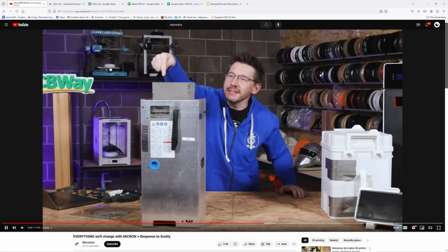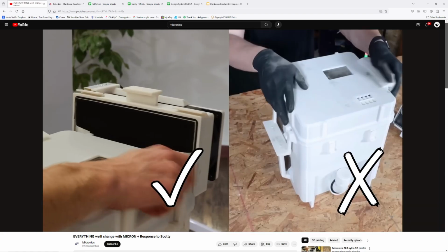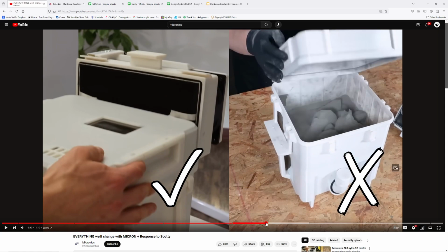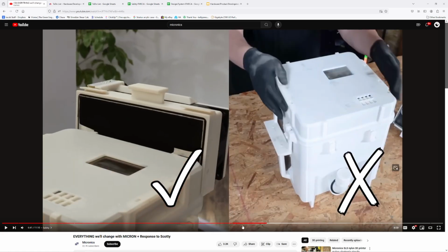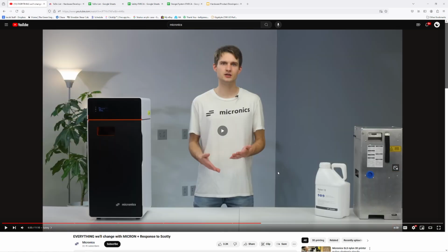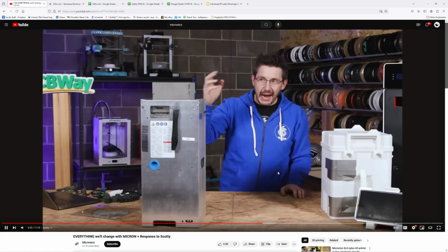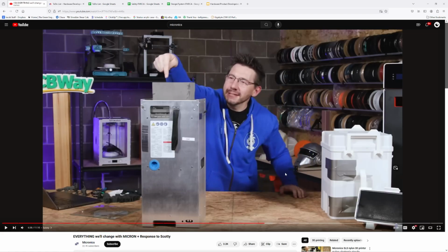First, the powder cake should never be lifted out without the scoop in place. So it should never be brought up without that scooper in place. But do you have an interlock to prevent that from happening? Clearly not. Joel here has lifted it up without the bin being there. So do you have a little limit switch that prevents you from lifting it up without that being there?